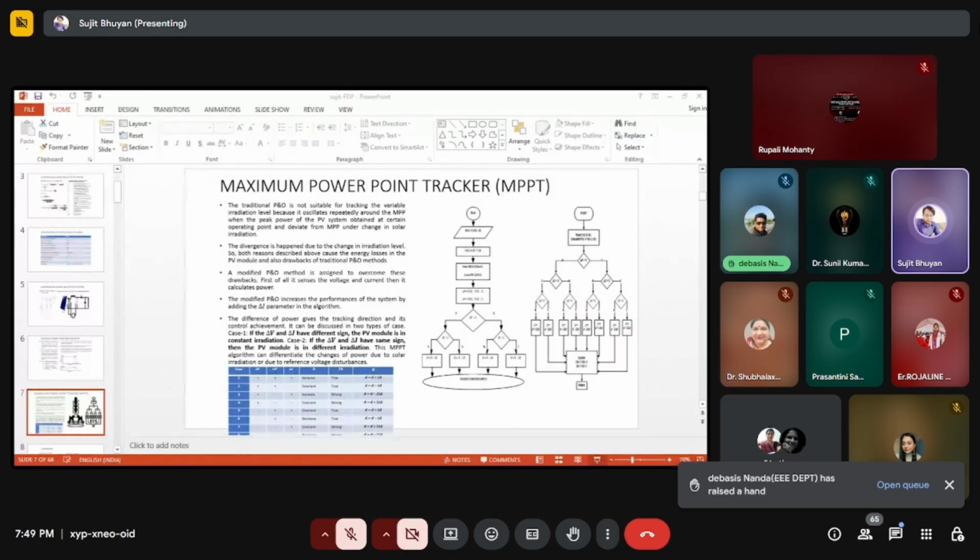This VD star and VQ star are compared with the VD and VQ generated by the ABC to DQ converter, shown as purple lines. These two signals are then given to the reverse conversion: first I took the rotating frame to the direct and quadrature axis frame, and now I convert the direct and quadrature axis reference frame back to the rotating frame, ABC. This generates the signals VA, VB and VC, which are given to the pulse width modulation, PWM.